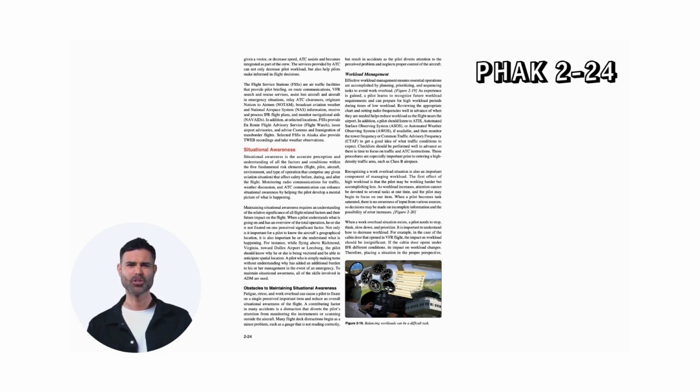Recognizing a work overload situation is also an important component of managing workload. The first effect of high workload is that the pilot may be working harder but accomplishing less. As workload increases, attention cannot be devoted to several tasks at one time, and the pilot may begin to focus on one item. When a pilot becomes task saturated, there is no awareness of input from various sources, so decisions may be made on incomplete information, and the possibility of error increases. When a work overload situation exists, a pilot needs to stop, think, slow down, and prioritize.